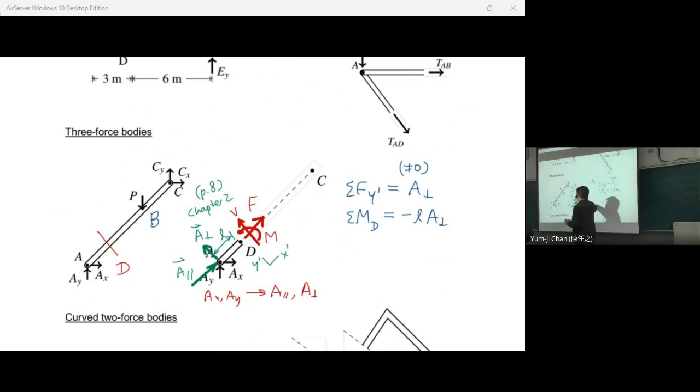So if we use the method for trusses, for example, cut this free force body at P. Of course, we need F here on this axis, but we also need one force V perpendicular to F and one M here. So let me write it down here.